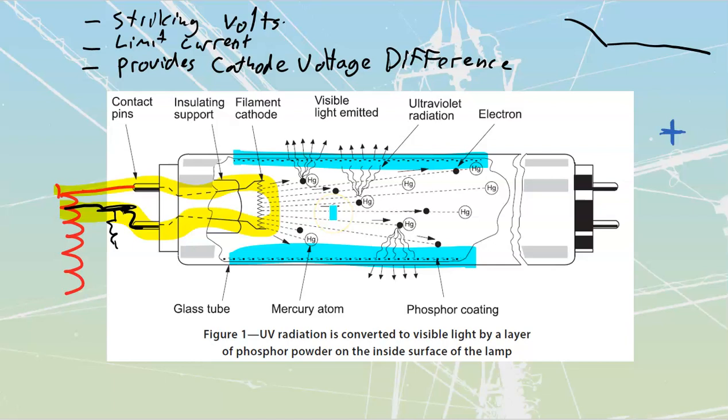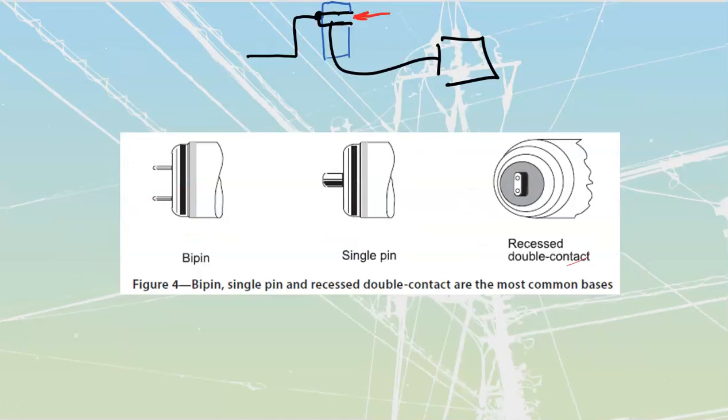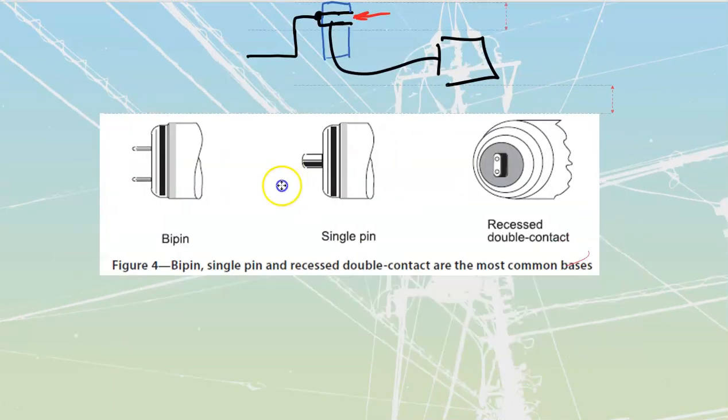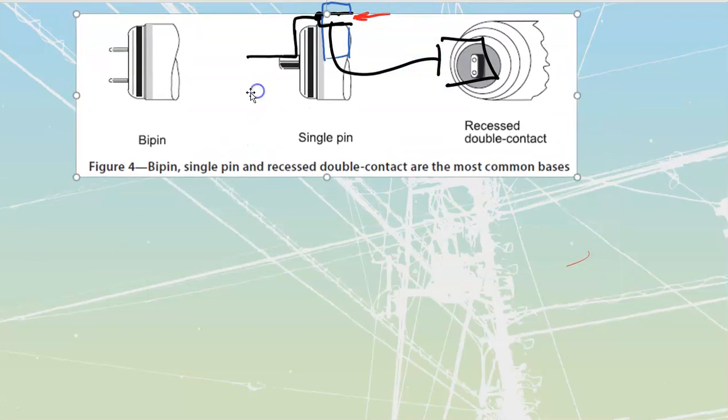And then stroboscopic effects are going to be something that is less common these days than what it used to be, probably more the 80s and the early 90s than towards the 2000s, because we were already getting to higher frequencies. Stroboscopic effects are the same as using a timing light to check a vehicle, where you've got a really high flash and then a low flash. What your eye does is kind of capture that, and it can appear that something is standing still when you're looking at stroboscopic effects.